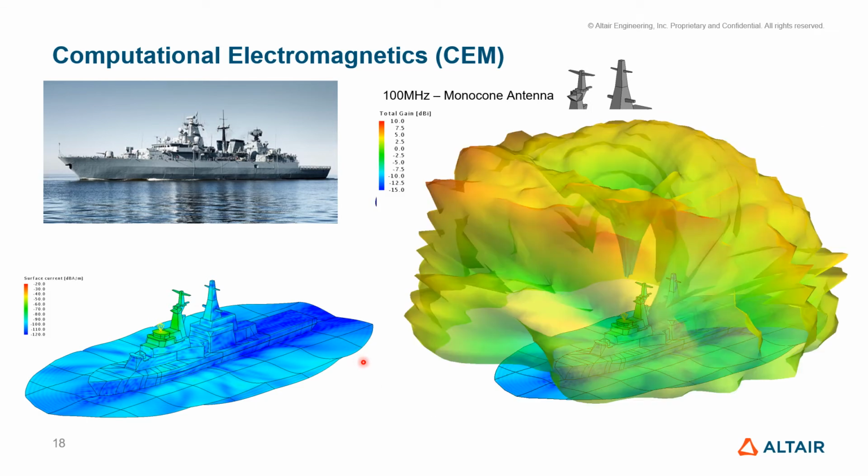The point we're making here is that once you have a CEM tool that solves Maxwell's equations numerically by discretizing, any object you bring in, you discretize. Once you discretize, it becomes a known element like triangles, tetrahedrals, voxels, etc., and you solve Maxwell's equations in those small elements and add them up.